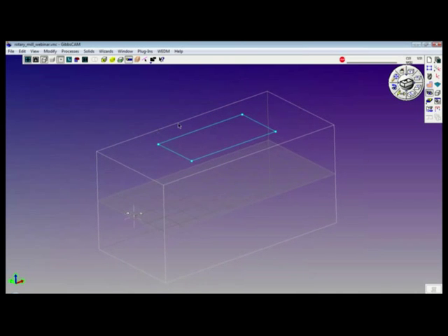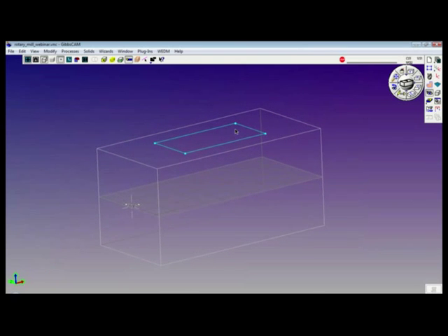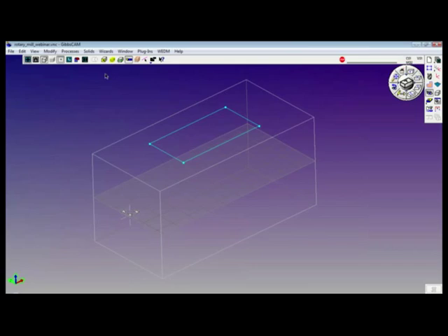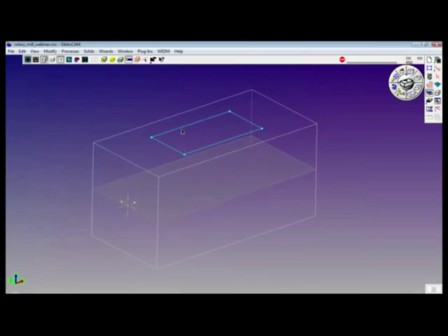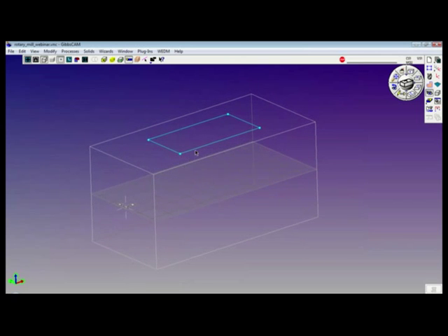Now, I mentioned that by checking off the rotary milling checkbox in the workgroups, you're able to wrap the geometry. And this is illustrated by clicking on this Wrap Geometry tile. You can see that the geometry wraps around that 3-inch diameter. Now, placement of the geometry is critical to the amount of material that you're going to remove in this pocket. If I was to move this geometry up or down, the radius of the wrap would change based on the radius of the part or the radius of the height.